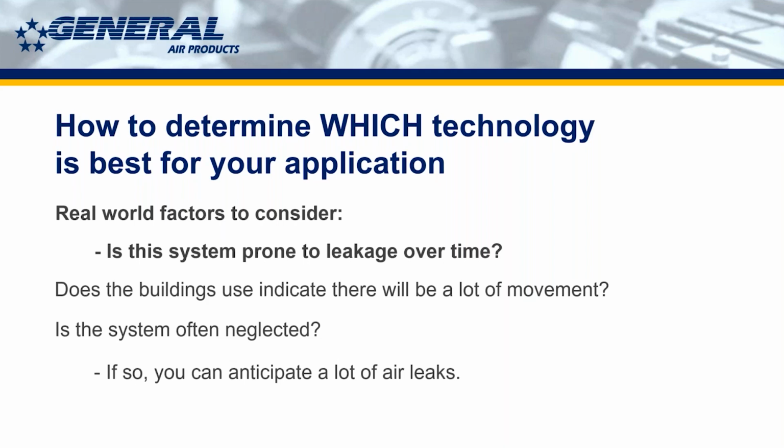It's a good question to ask yourself, because again, the whole point of nitrogen is to reduce the amount of corrosion so that you're not in there replacing pipe all the time because of significant corrosion. But what if you're in there chasing air leaks instead? Is that not just as expensive, just as time consuming, or just as problematic? That's why we're asking this question. Is the system prone to leakage over time? Non-corrosion related leakage.